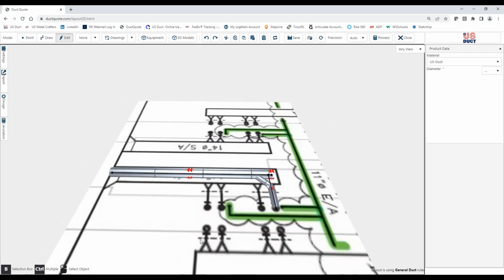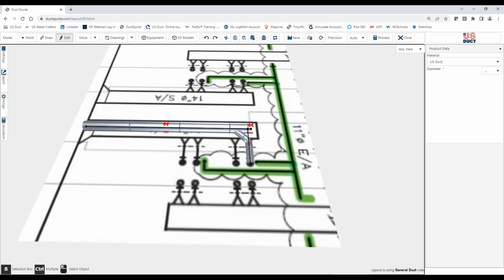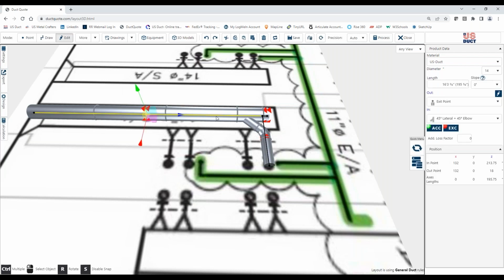Now what we've got here is an example. I have not drawn this to height, but it is very easily demonstrated. What we've got here is a trunk going back into a larger trunk. And this is our first drop. Each of these is where they wanted to locate a hard connection. So I'm going to show you that here we've got, I believe it's a 14, yep, inch trunk or subtrunk, if you will. And here we've got an 8-inch drop.